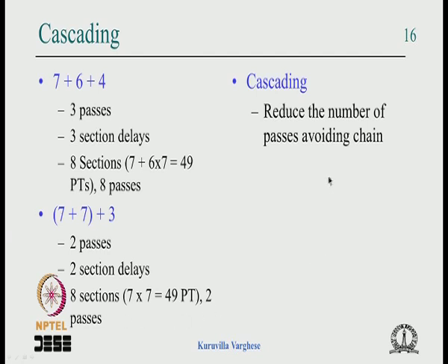So the tools, when they map the circuit to this, always make sure that it is kind of balanced. It is always like 7 plus 7 and so on, and they combine everything together in a last section, okay, depending on the constraints of the number of product terms in each section which is available, okay.